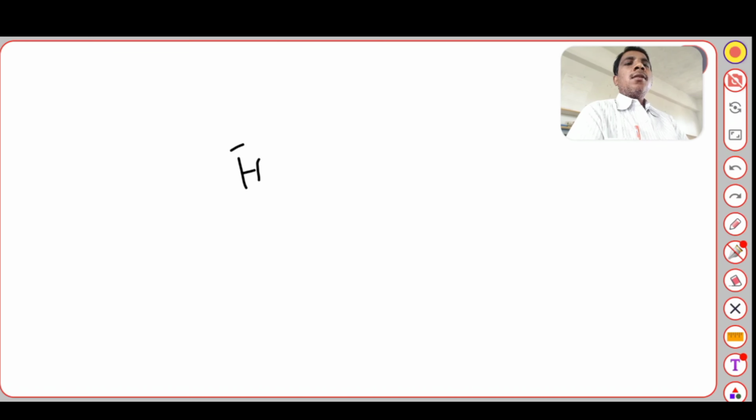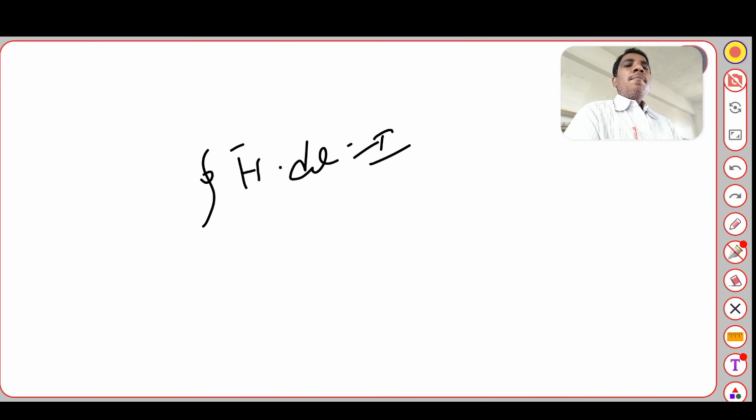Ampere's circuital law states that the line integral of H dot dl, the line integral of magnetic field intensity over the length dl, that is closed line integral H dot dl, equals I, the current enclosed by that path. This is also known as Ampere's work law, which we also discussed previously.